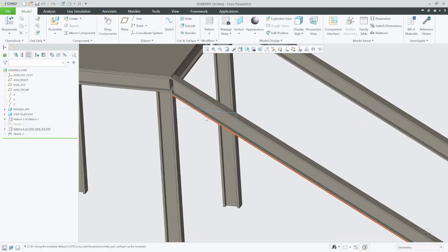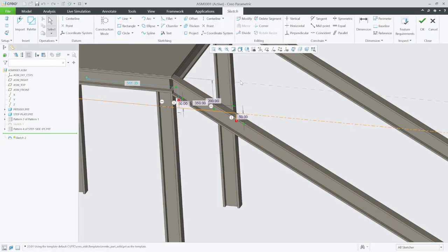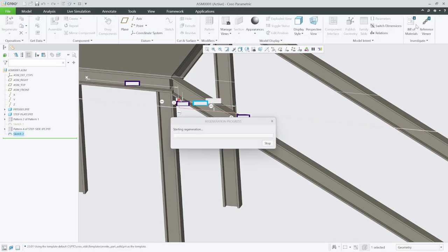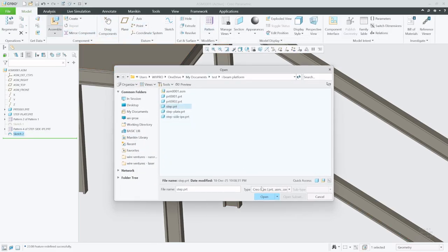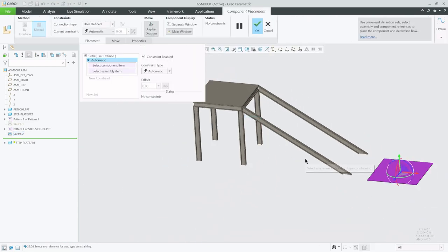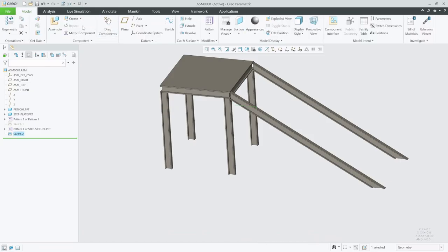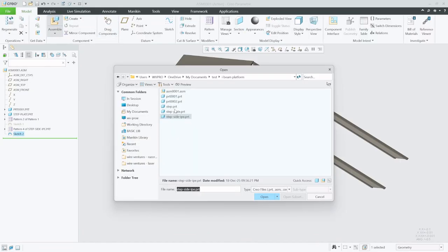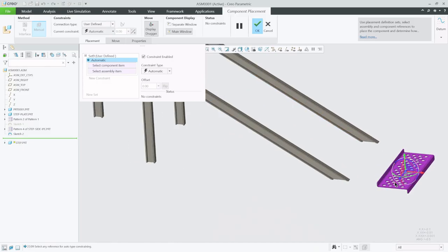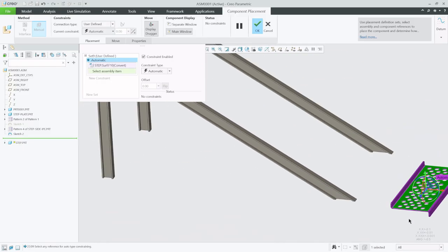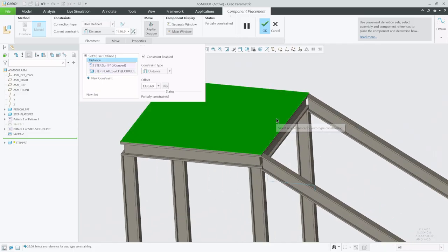We're going to hide this. Well, actually, let's just check first. So 200 was our size. Okay. So now we can insert our step plate. So open. Sorry, guys. The step, not the step plate. Step plate's the one on top there. Okay, so what we're going to do is first we're going to say this one and this one. Distance is 200.